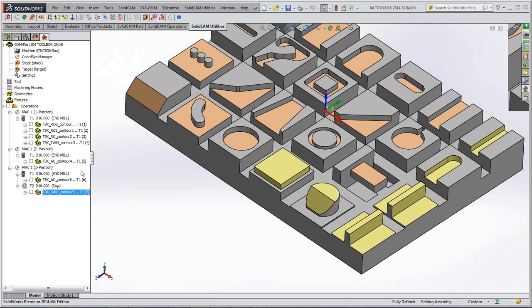Another little toolbox cycle that I think you may be interested in is the way we enter an open slot. Previously, and even existing now, you can go into an open slot. When you do an open slot, you just approach it from the outside with the full width of the cutter, the centre of the cutter line, and machine through in the traditional manner. But there's a new option now being added, which is called the roll into open slot method.